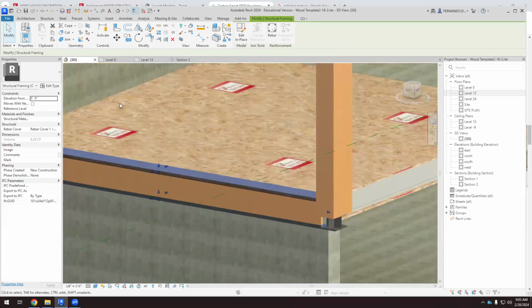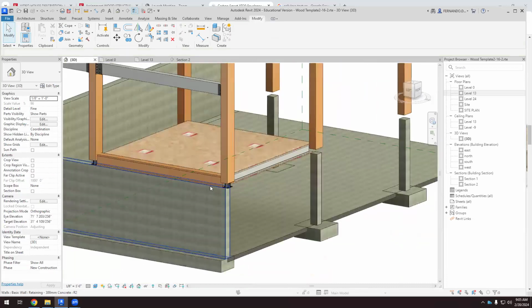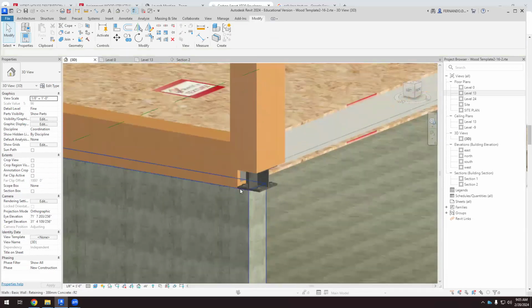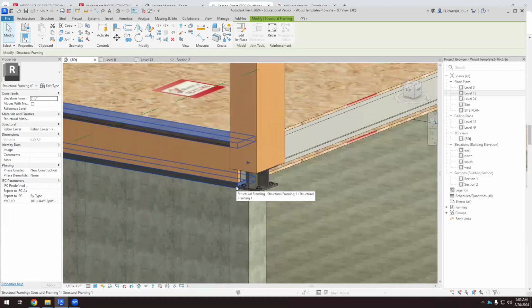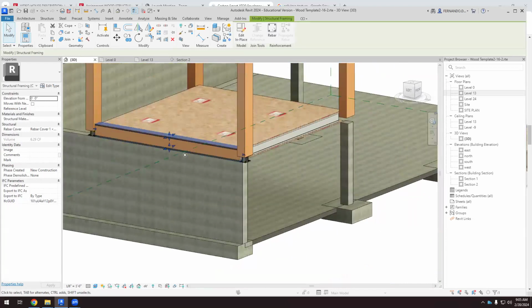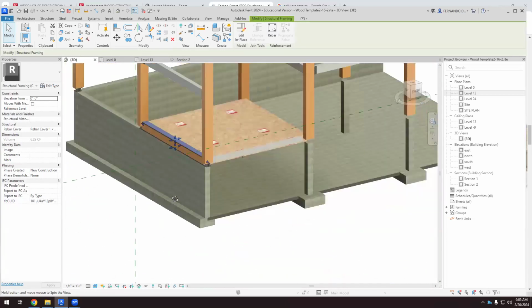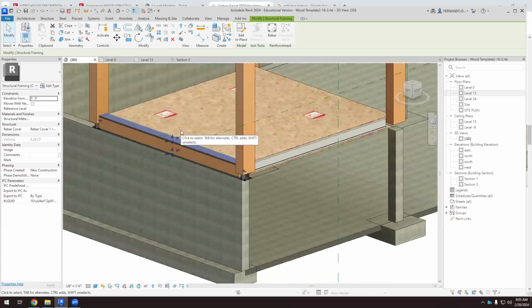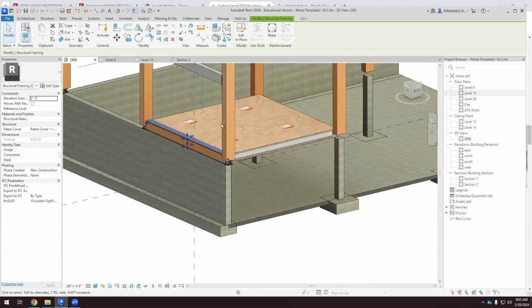So I can copy the element itself, but I think if I change the extrusion, it will work better. Other years, we have had trouble copying elements that we have created with the component model in place option. So I think that works better. Maybe I'm wrong, but I think that works better.